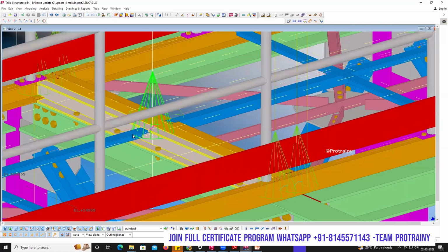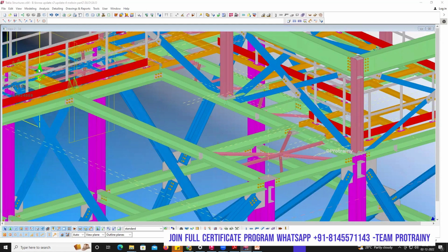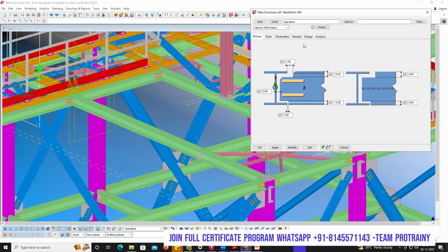And coming back here, you will have connections. So based on that, you will be working on that. As I said, if we are working on the new notch here, as this is the I-beam, and in this beam we are adding a kind of component, you have to get a weld here. So based on that, you have to give the clearance. These things have to be known by a person who is very experienced.